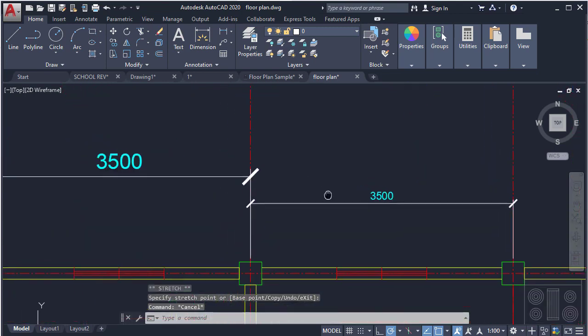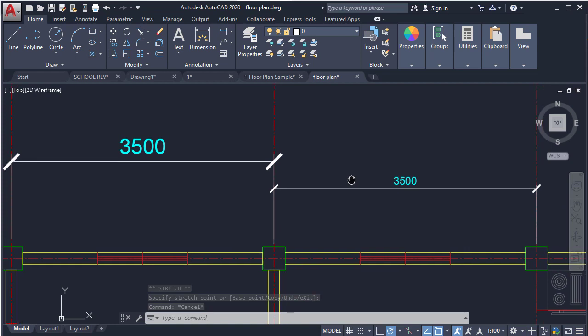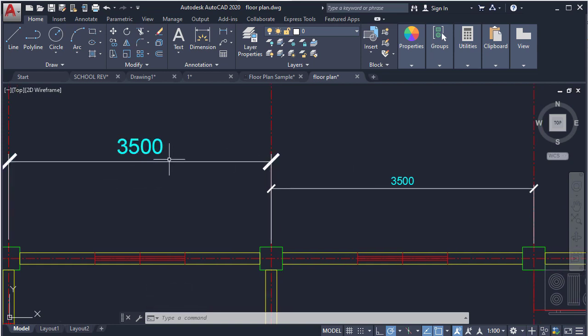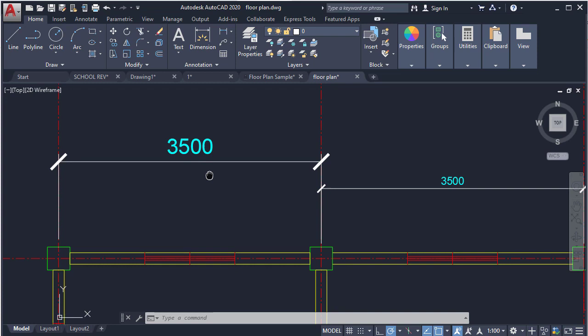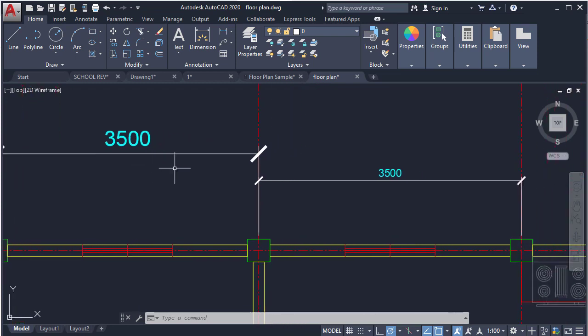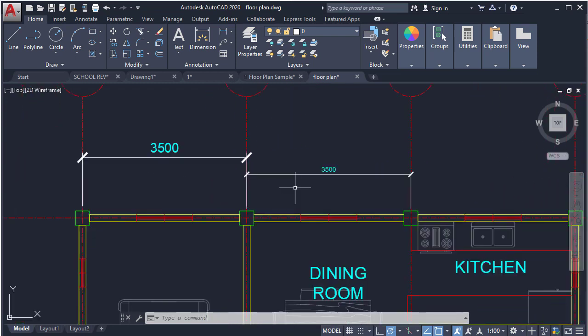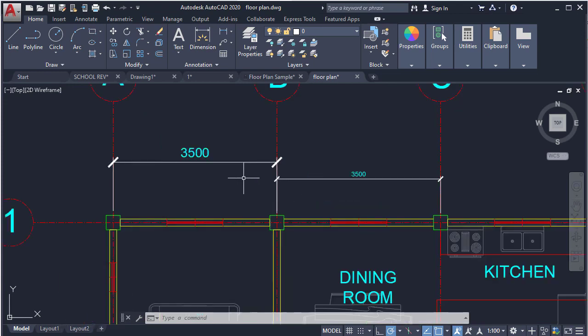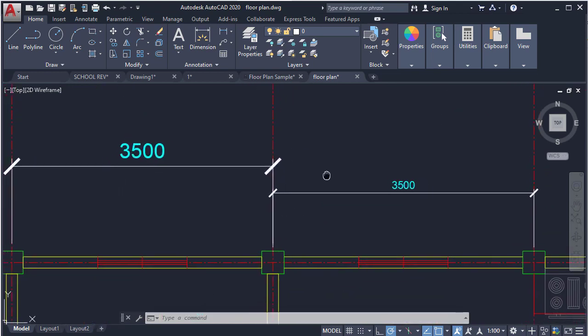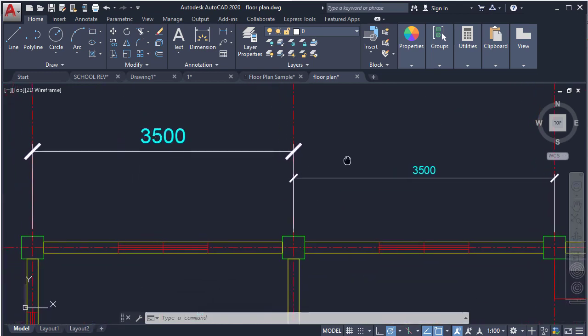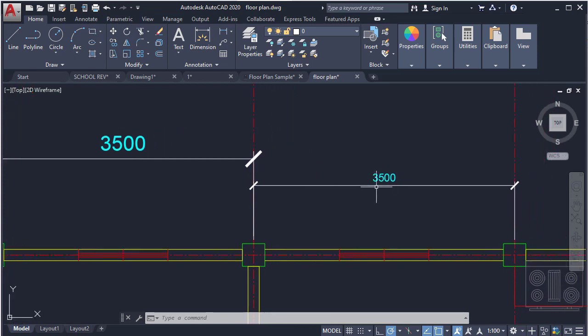If you notice, the key difference is the size. It generates the same value, but the height of the text, the size of the arrows, is half of the dimension size of the 1:100 scale. The reasoning for this is once we set this one in our layouts, we will now have the appearance that is proportionate to the appropriate scale that we have placed. More of that in part 4.